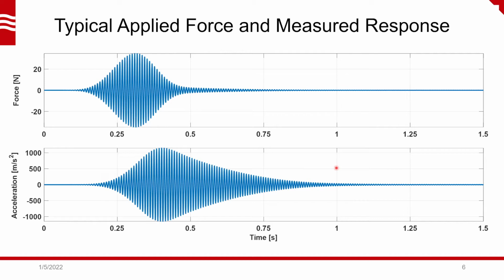time. So what I'm doing here is I'm applying isolated sine beats to each of the first three modes of the structure to excite them individually, and then to see what sort of quasilinear parameters they have when they're excited basically on their own. And then I'm superimposing sine beats to excite two different modes at the same time, and then just checking how the identified quasilinear parameters change when other modes are also excited.